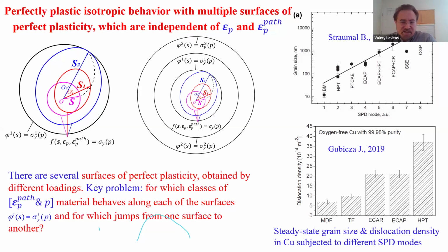And then one more question appeared: how to distinguish amorphous phase from melt. Well, by definition, melt does not have shear resistance. So what we obtain is that shear stress drops to 0. For us, this is melt. I call this virtual melt. We have dozens of papers on virtual melting. That means that the material melts at room temperature, 1000 degrees below the melting temperature. This is in silicon, in copper, in aluminum.